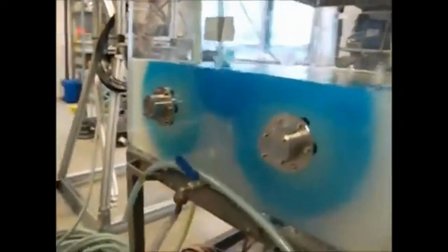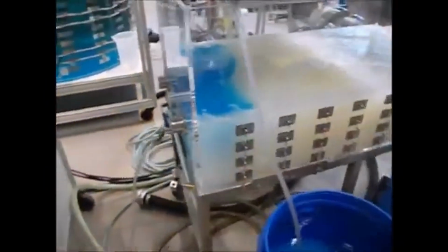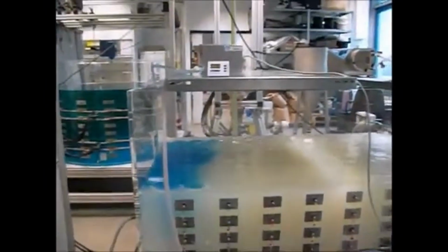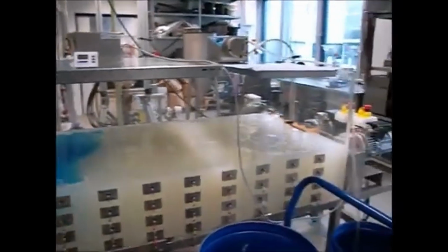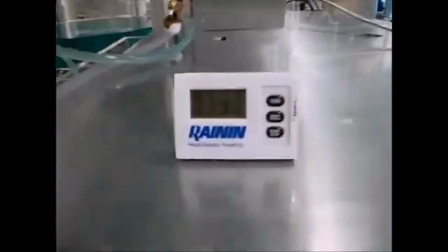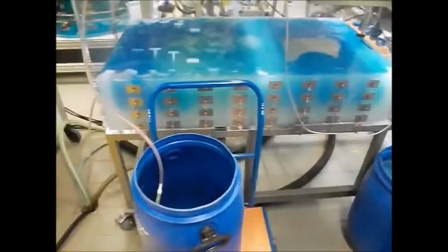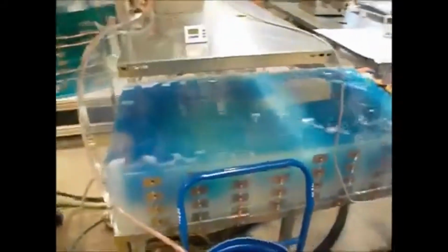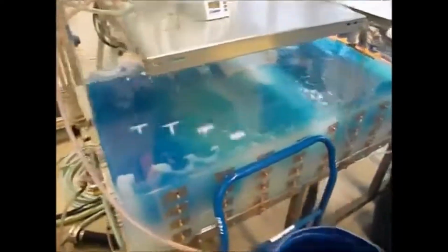The plug flow model has many practical applications. One example is in the design of chemical reactors. Essentially, no back mixing is assumed, with plugs of fluid passing through the reactor. This results in differential equations that need to be integrated to find the reactor conversion and outlet temperatures. Other simplifications used are perfect radial mixing and a homogeneous bed structure.